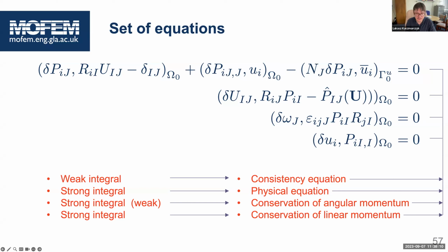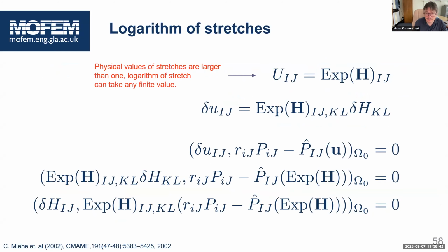There are formulations for small strains which build the tensorial H-div space such that they guarantee symmetry of the Cauchy stress a priori. However, they do not necessarily give you any advantage, and this formulation gives us more flexibility. But here we can deploy one additional, unusual trick.